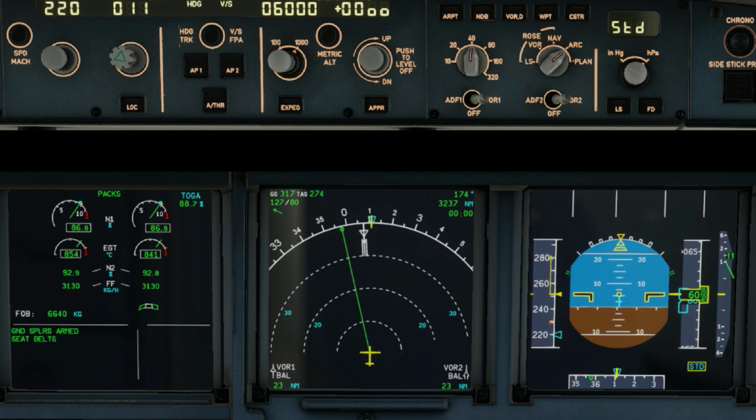Okay. Now this demonstrates one of the limits of home video games and flight simulators, because this behavior is a perfect demonstration of the correct 737 behavior. So if this were a 737, this would be absolutely correct. A little tendency which is immediately compensated by the autopilot. Now as you see here, as we keep accelerating, the aircraft keeps 5 degrees, so we find ourselves exactly in the same position where we were with the 737. The autopilot is maintaining constant pitch.